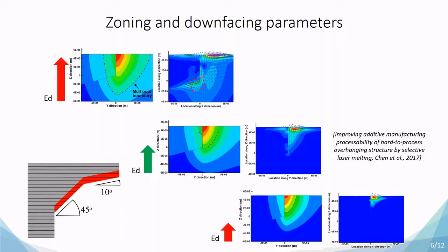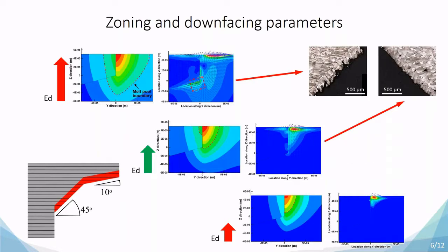But then in the XY direction, we don't reach the minimum length required for supporting the next layer. So when using optimal parameters, we obtain a surface which is homogeneous, which has minimal surface roughness, and more importantly, which is, well, theoretically, hopefully void-free.